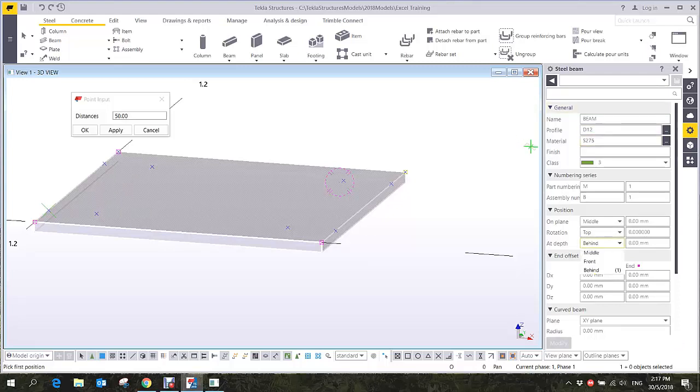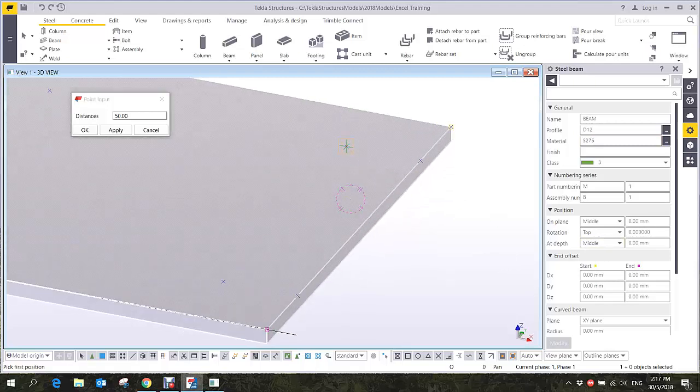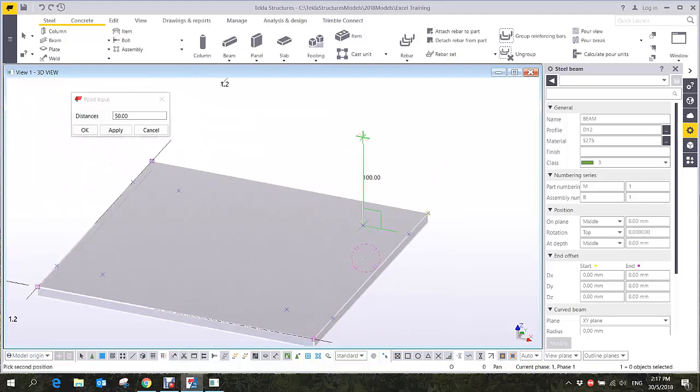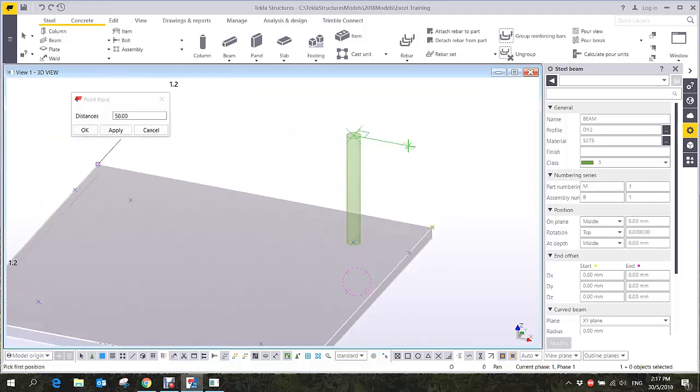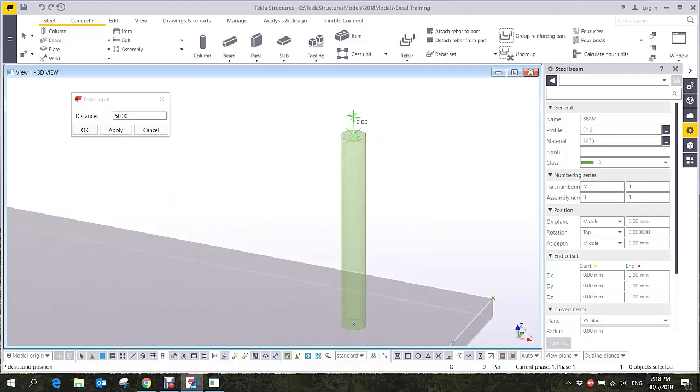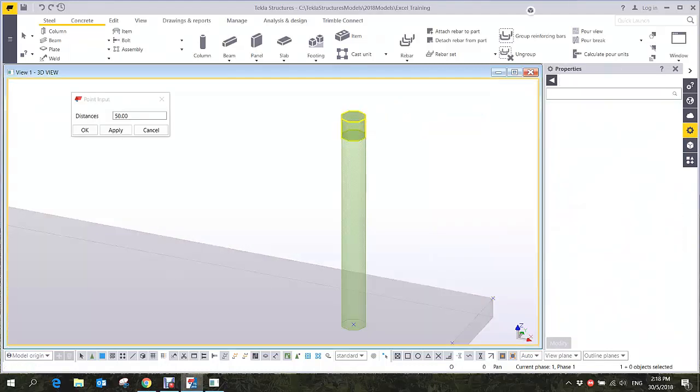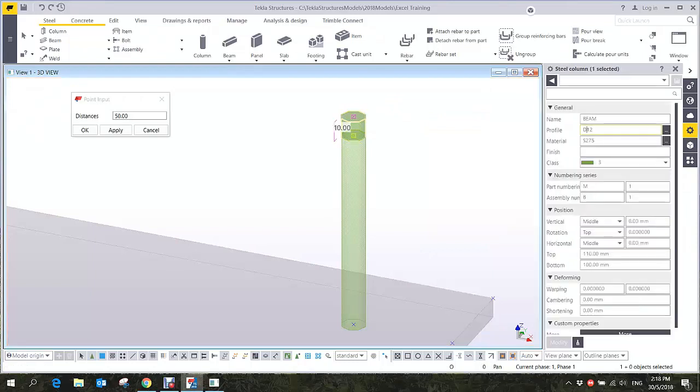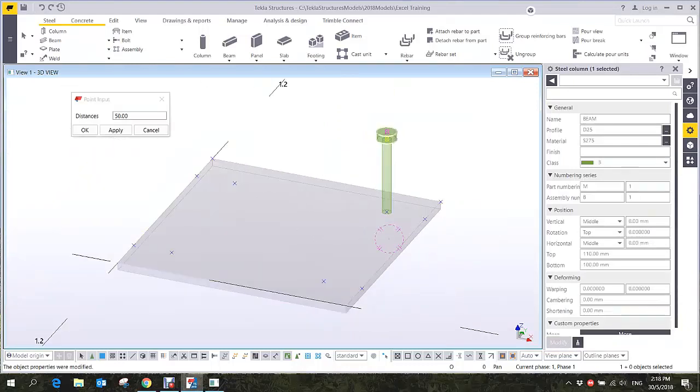Okay, so middle. If I look, I can easily click on that position, right? So what is the height? Let's say 100. So I have diameter 100, and then here, let's say I want to have a 10 thickness, but this one will be diameter 25. Modify. So now I have the stud.